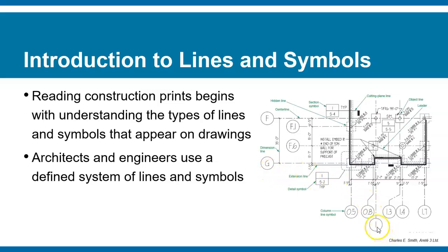This is center line 1, and it's intersecting with center line F.6. And from that center line, the exterior, or from F to G, those are referenced each other of 13 foot 7 inches apart. Okay. So that's how you would interpret that.